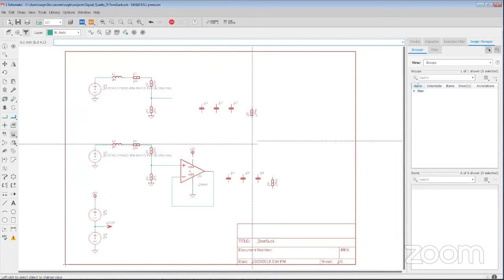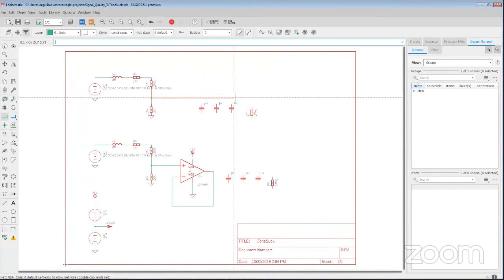Nice. So let me go ahead and fix a couple little things here, make a few connections here. Okay. So what I'm modeling here, again, we have these multiple capacitors, which again, I could really replace with one. And if everybody is okay with it, and we understand that this capacitor is going to represent the total capacitance in the wire, if we can clear that up and everybody's okay with that, then I am going to replace these with just a single capacitor because it'll just be clearer. It'll be easier, I think.